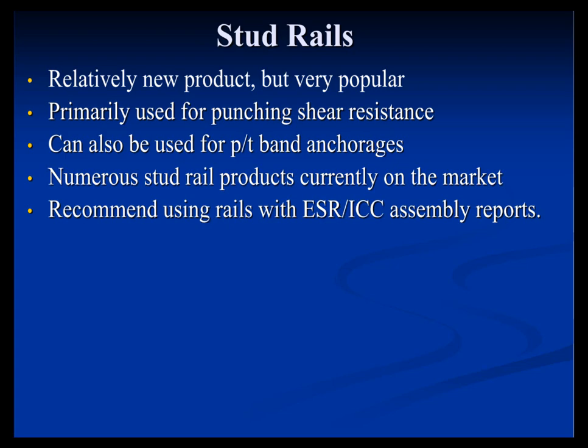When I show you the photographs, if you have never seen one, it's effectively a stud welded to a rail. The problem is when you just have random studs, let's say, to be dramatic, welded to a rail, there's no assembly report. There's no way to justify the strength of the system itself. The pieces and parts, fine, whatever that is. But the actual assembly, the whole widget, is not documented. So that puts all the legal responsibility on you as the engineer of record if you accept that.